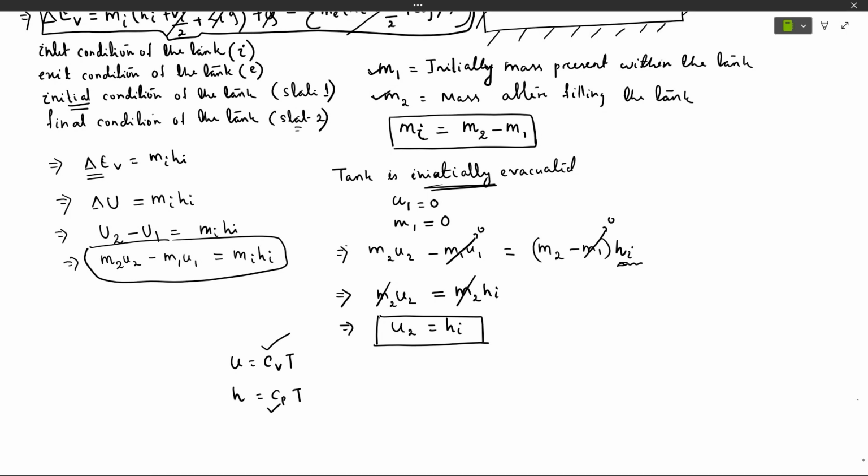Let's consider u2 as C_v T2, that is equal to h_i, that is equal to C_p T_i. So T2 is the final temperature of the air after filling the tank.